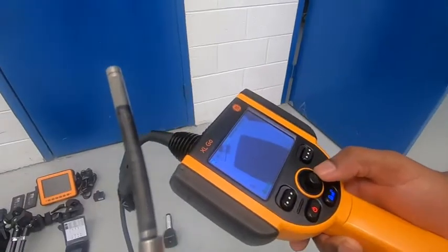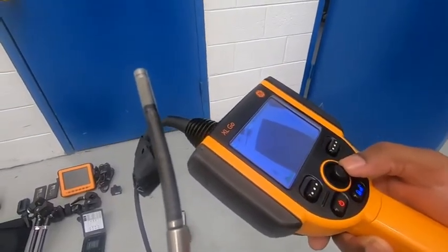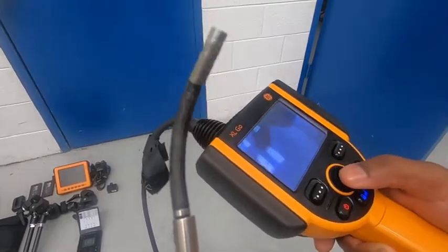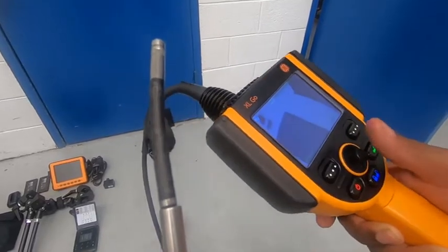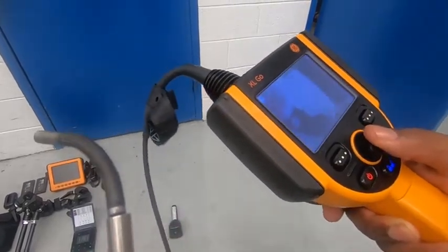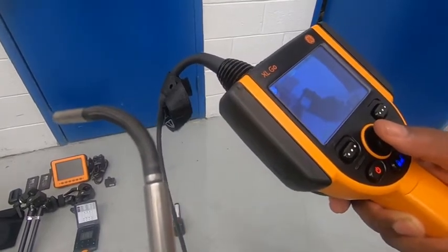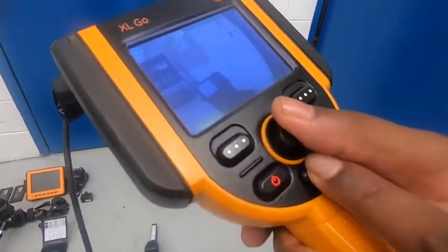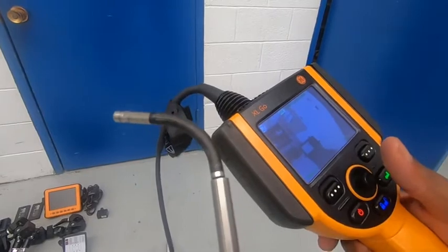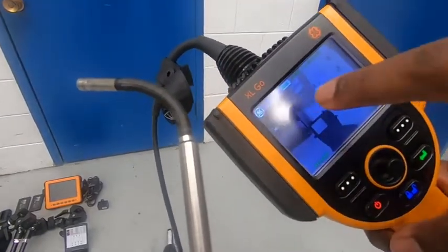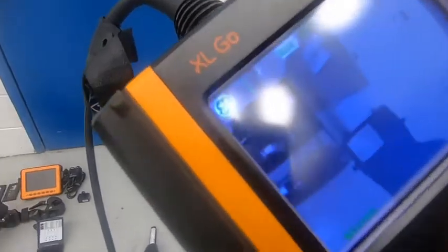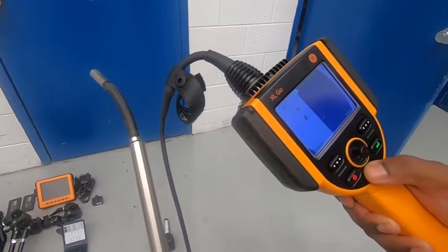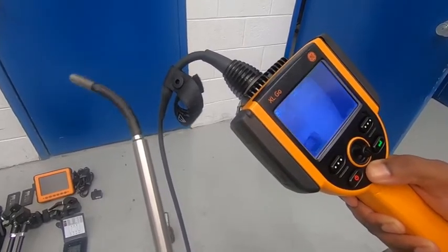The joystick controls movement of the articulating section of the insertion tube and is used to point the viewing tip where needed. The freeze/enter key is used for freezing or saving an image on the LCD screen and for selecting options on the screen. Pressing the steering control key activates the articulation lock for holding the viewing tip in the direction selected with the joystick. When activated, a lock icon appears on the LCD screen. Pressing the key again releases the lock. Pressing and holding the steering control key activates the home function, which straightens the probe back to a neutral position.